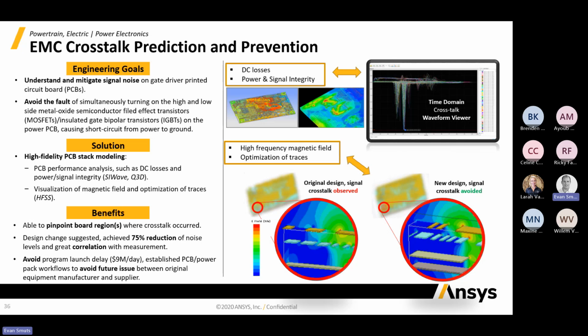And then we can take that design and actually predict phenomena like crosstalk between neighboring trace lines fairly easily. We can start creating contour plots, as we can see up here, top center, where we can get visual feedback as to where the problems are occurring. Okay, and then it takes a lot of the guesswork out of where the problems are coming from.